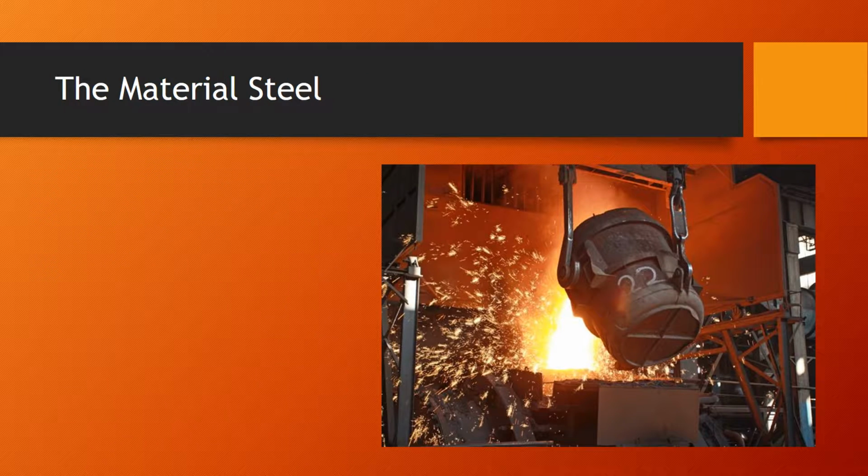The material steel. Steel is any range of iron alloys that contains less than 2% carbon. Structural steel, or mild steel, contains less than 0.3% carbon and other trace elements. In ferrous metals, iron-based, too much carbon makes hard, brittle steel, or cast iron. Too little produces malleable, weaker material like wrought iron. Mild steel was optimized for structural steel by controlling the amounts of carbon.